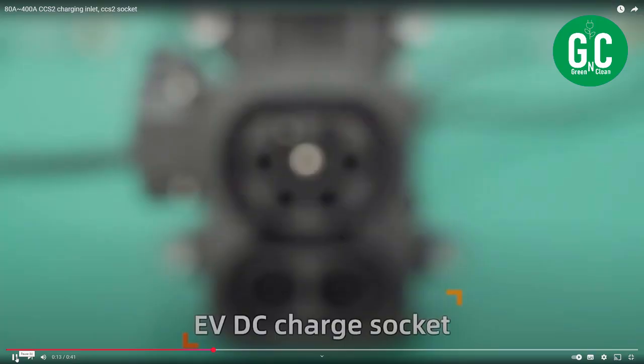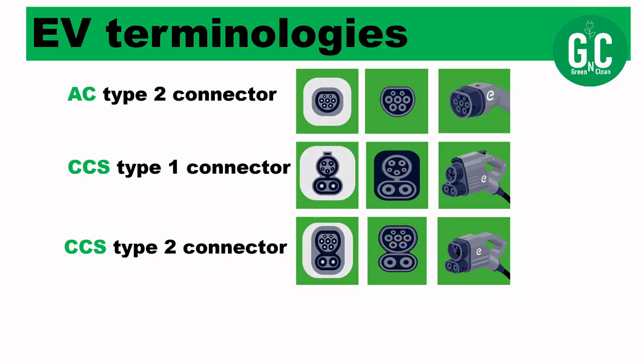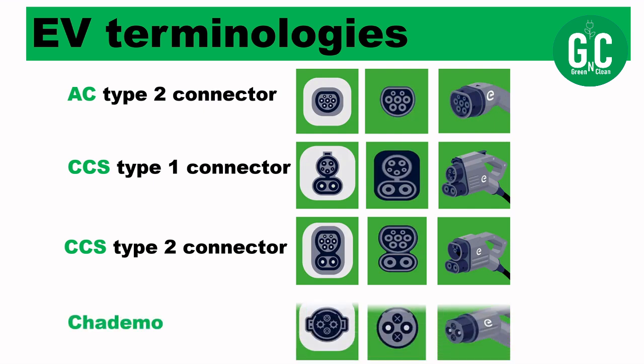What's commonly used in India or Europe is CCS type 2 for DC fast charging. You can see the plugs here. It's got this unit where the top half looks like an AC type 2 connector with two more holes at the bottom. And these are used for DC fast charging. You can go all the way up to 350 kilowatt of charging with this type of connector.